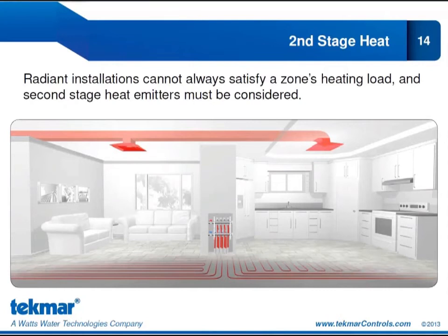Now, typically when we talk about forced air heating, the supply water temperatures are higher than we would like to see for a heat pump application. Remember, we typically recommend, based on the refrigerant that a heat pump is using, that the design temperatures are no higher than 120 degrees Fahrenheit. Well, usually when we're talking about forced air, the design temperatures are higher than that. So we have to take special consideration in the types of terminal units that we're choosing for our second stage of heat when we're doing a geothermal application.